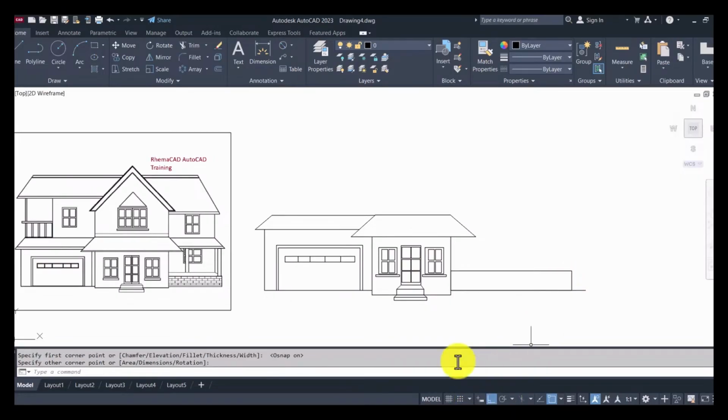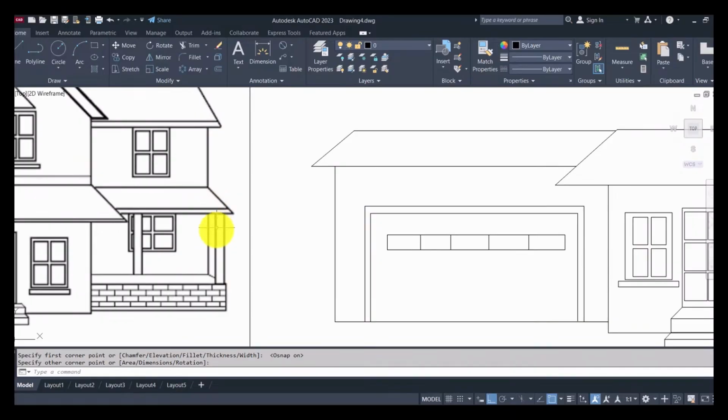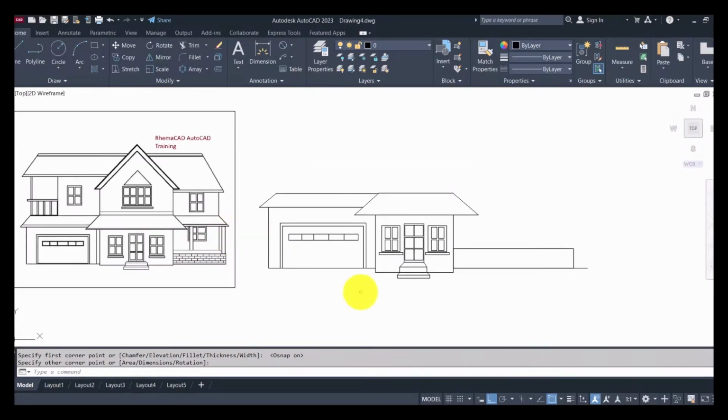Okay, then, this is a column. So rectangle, column, off object snap. Put off the object snap so that I can pick this point. It doesn't have to be accurate, as I said. Accuracy is not a major concern for now.